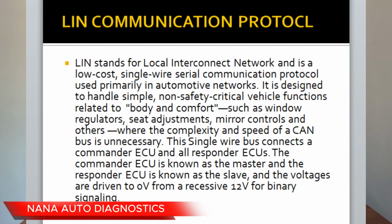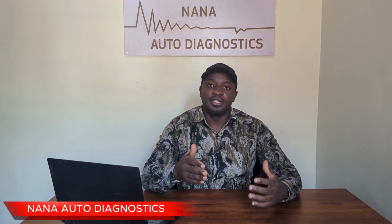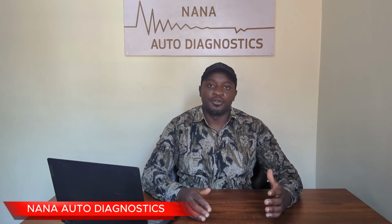The single wire bus connects a commander ECU and all responder ECUs. The commander ECU is known as the master, and the responder ECU is known as the slave. The voltages are driven to 0 volts from a recessive 12 volts for binary signaling, and we shall explain that in detail later on.